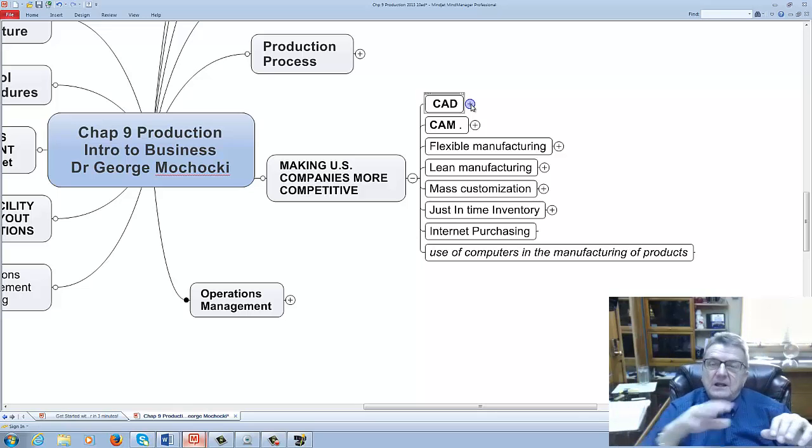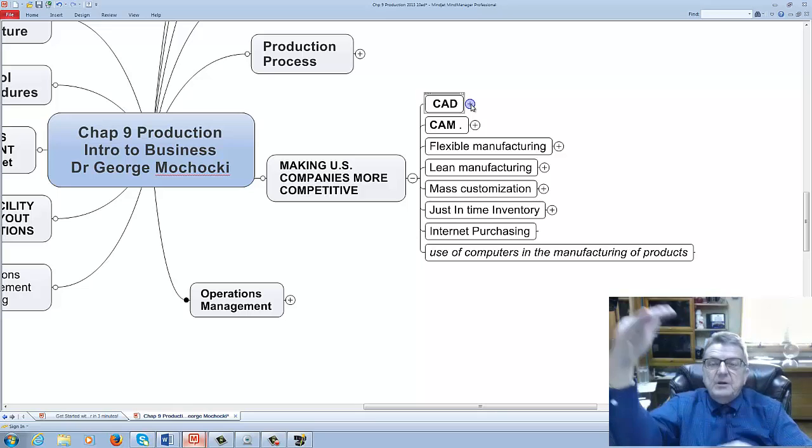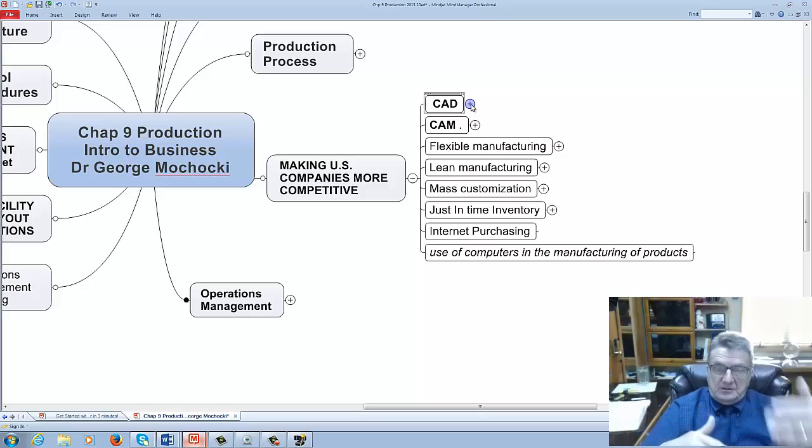By doing it in AutoCAD, I could just peel off the things. I send them an electronic file. I could send it to another person to evaluate, put all the specs on there. I could do a lot of things to be a lot more cost effective. When I come in there, I just peel off all the layers, and I just got to look at the plumbing. And I got to look at the electrical and see where there's any kind of clashes, okay?